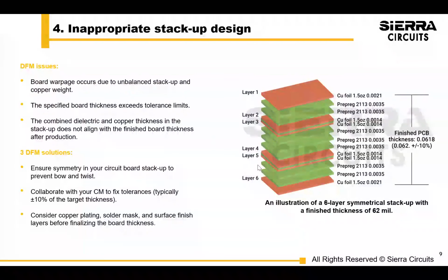So again, a material just based on the data sheet is not good enough. In our material selector, we have some more attributes for the materials, like, is this material suitable for blind vias and sequential lamination? Is this material suitable for solder mask? We have these extra pointers because picking a material by looking at the data sheet by itself is not enough.